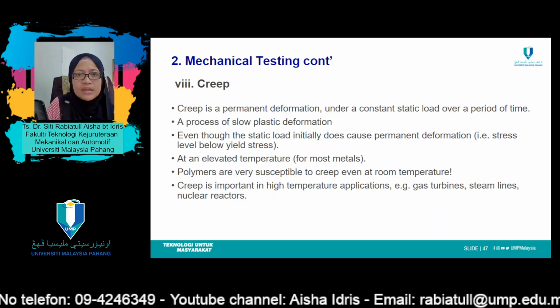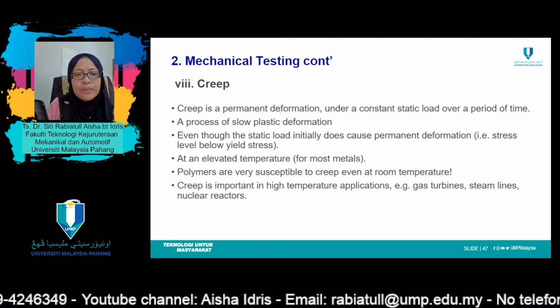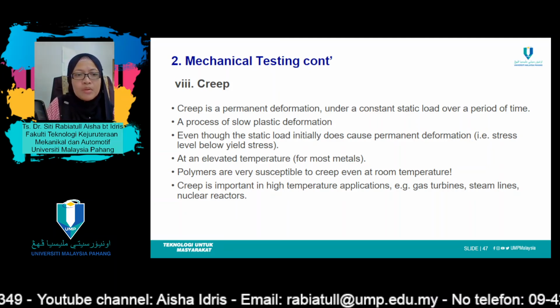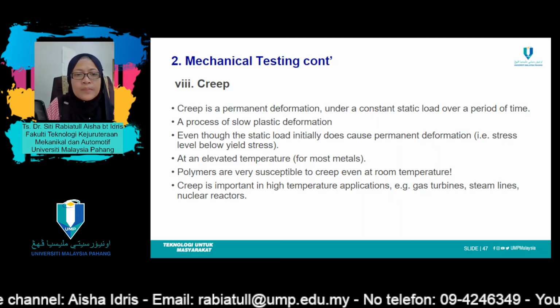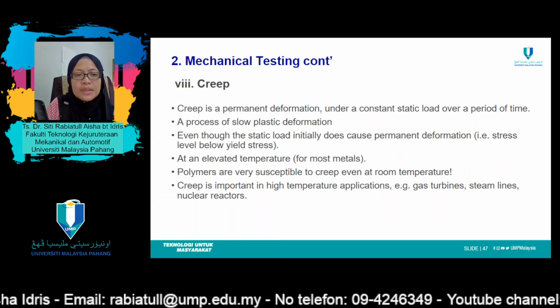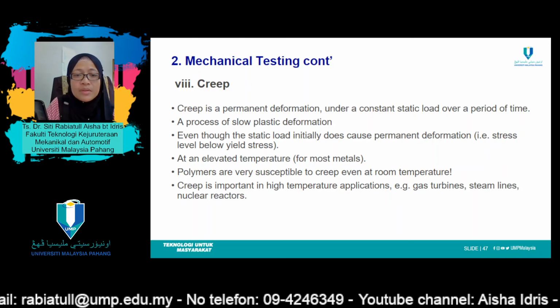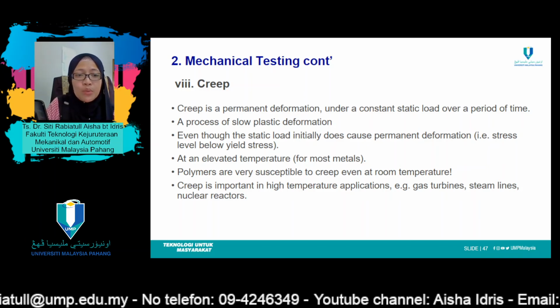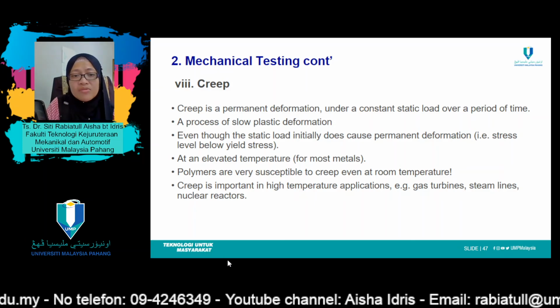Okay, the last testing in this topic is creep. Creep, sometimes referred to as a stress relaxation test, is used to determine the amount of deformation a material experiences over time while under a continuous tensile or compressive load at a constant temperature.